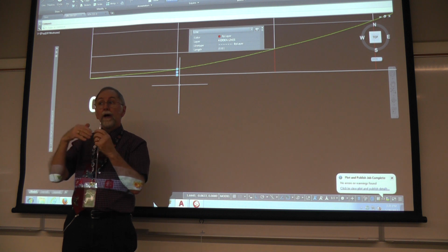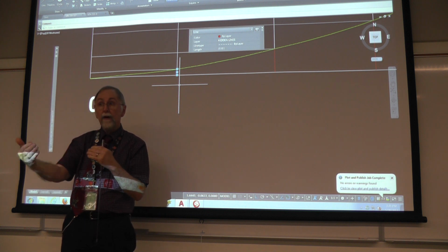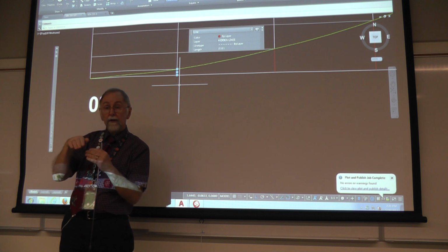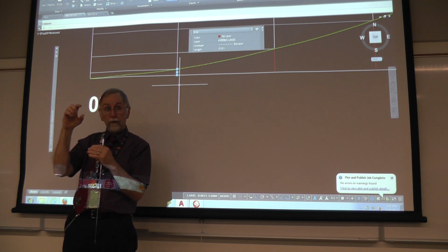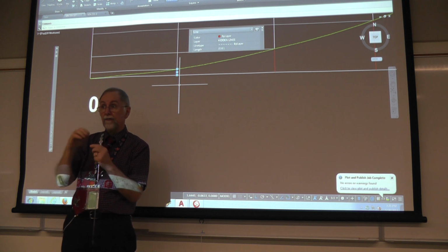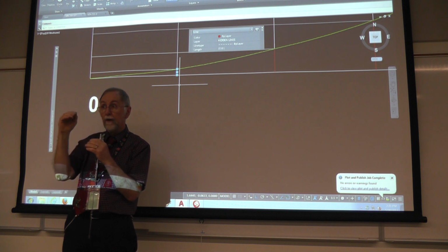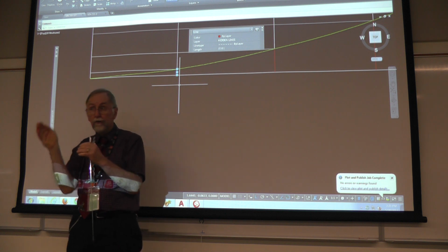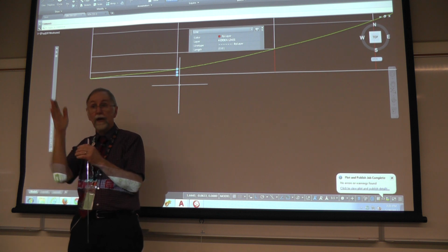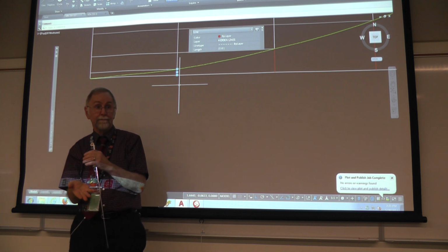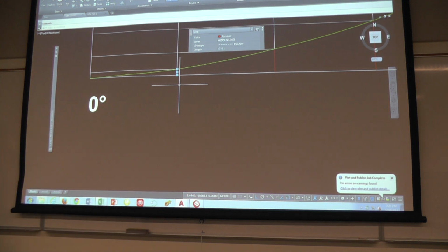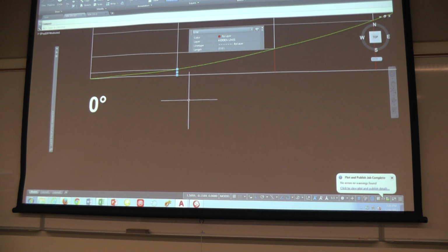So if I go off of the prime circle, which denotes the bottom, I'm going to go half the diameter of the roller. Right. So the diameter of the roller is a 1/2 inch. If I go a 1/4 inch off the prime circle, that will establish where the center of all my cam followers should be as I rotate them around by 18 degrees. So your first one is half, right, and that's 0. And then go from there. Great. All right. So let's remind ourselves it's 0.0381.